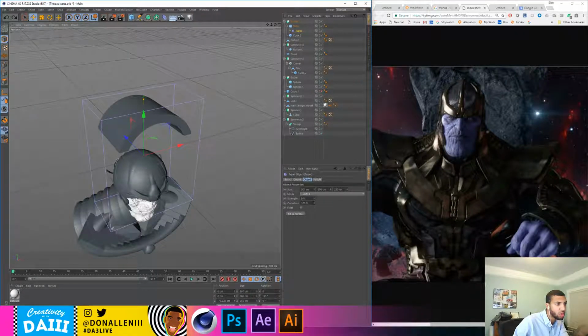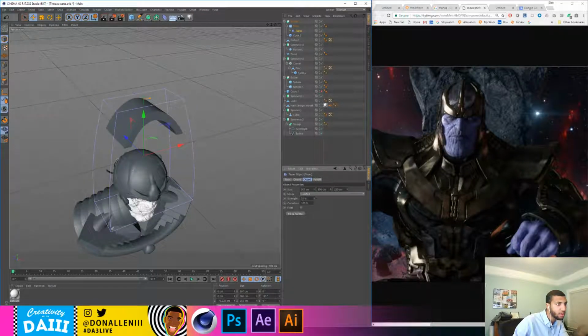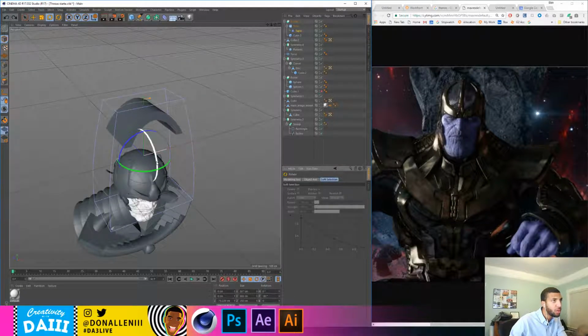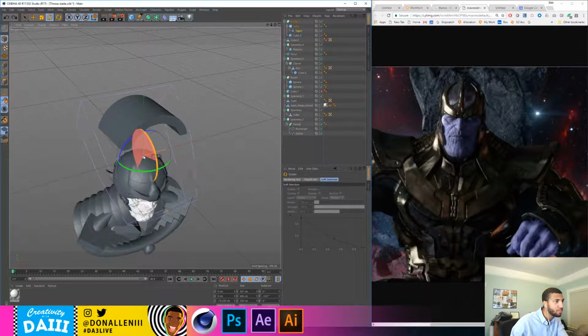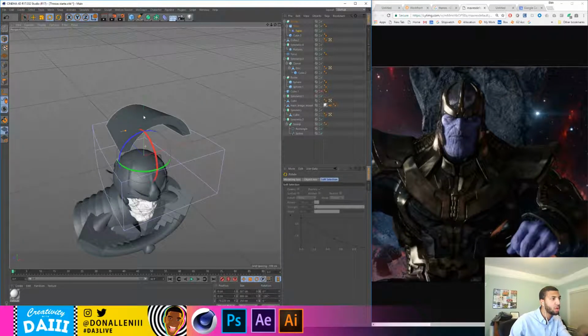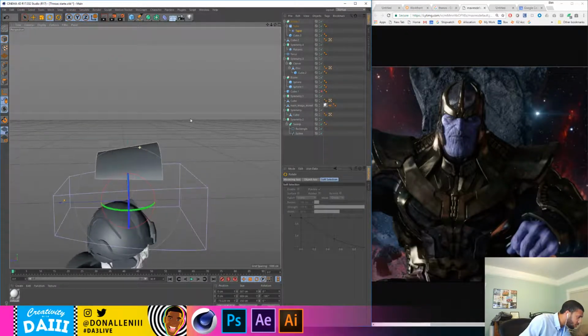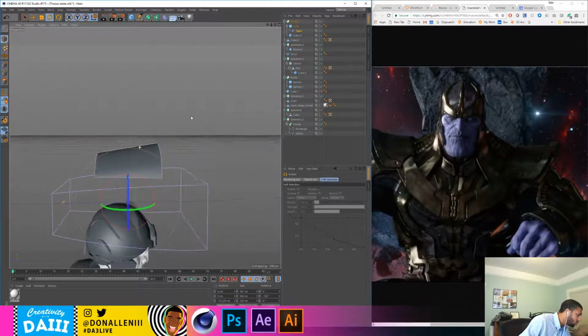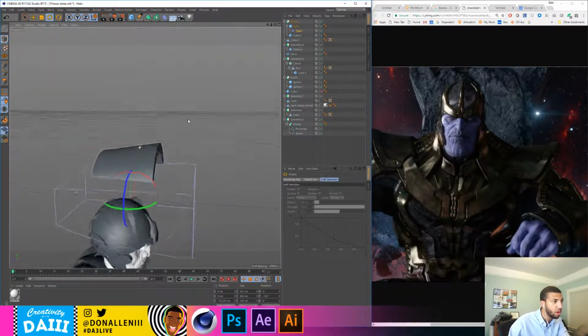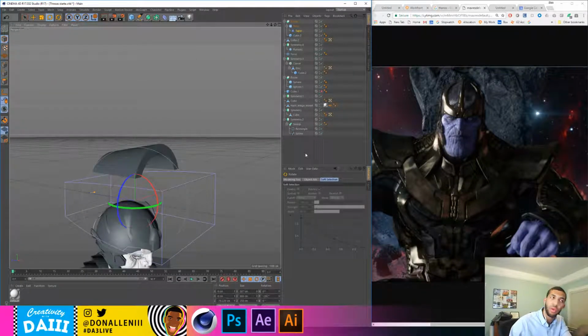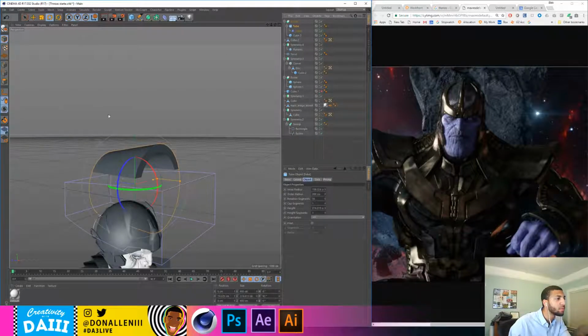What we'll do is we'll bend that like that, and then we'll rotate it. Shall we rotate our bend deformer this way? Just 90 degrees. The reason why is it makes this cuff have an angle to it. You can almost imagine using this technique to make the tiles on a roof, but I'm going to use it to make a shoulder plate.